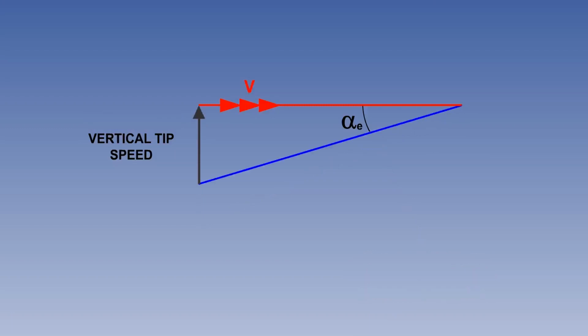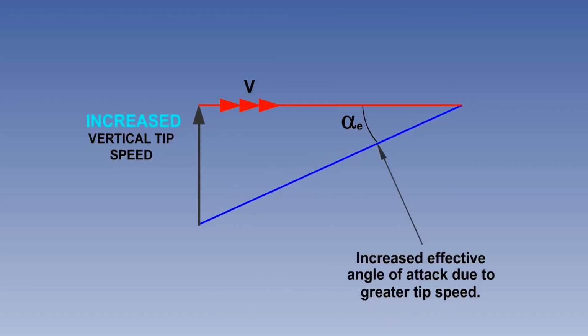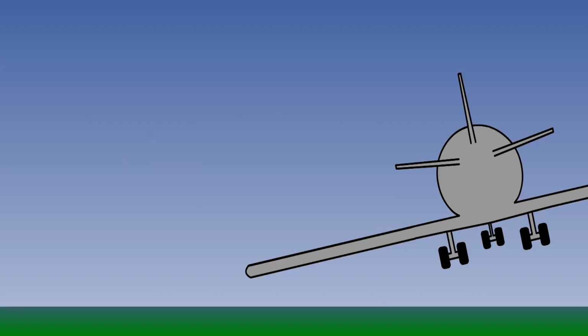The greater the effective angle of attack at the tip, the more will be the resistance to roll. This phenomenon is known as aerodynamic damping, and will be covered in greater detail later in the syllabus. A long wing will allow less wingtip ground clearance in manoeuvres close to the ground during takeoff and landing, which could be a significant factor in a crosswind or gusty conditions.